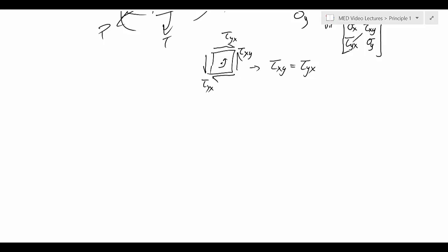So at a particular location, it is convenient for us to have an axis where we can find a maximum stress value with respect to that axis. But it's certainly possible that the axes that we just happen to have chosen aren't necessarily the axes at the orientation where stress is highest. Now, we don't really care about the stress in the orientation we chose. We care about the stress where it's highest, because that's what's going to lead to failure.